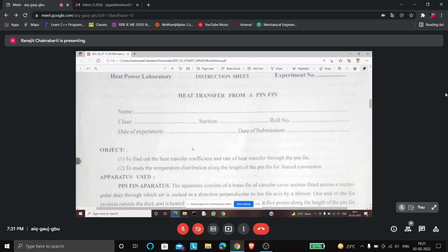But between the fluid and the hot surface, we have to have fins. In air conditioning, now I am coming back because air conditioning is the field where I have worked, I have seen lots of fins there. It is a must for having effective, augmented heat transfer rate between the chilled system and the air. So fins are very important.